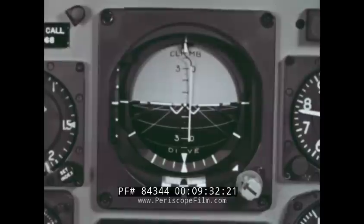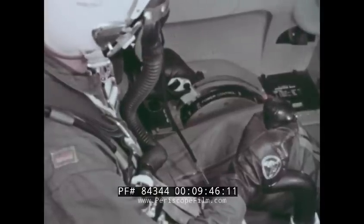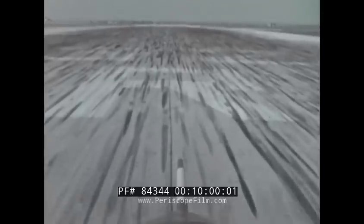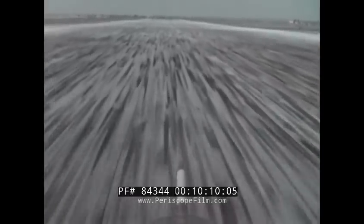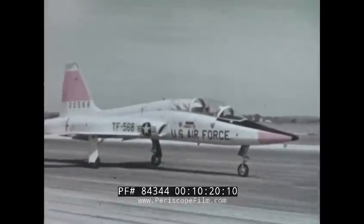Recheck your bank steering bar to see that it's centered. This bar will be used to maintain directional control during the takeoff roll. The instructor has turned over the controls to you, and you're ready for takeoff. To the instructor, the takeoff roll looks like this. But all you can see are the instruments. Just keep the bank steering bar centered, and you'll take off down the middle of the runway. Remember that the bank steering bar will only bring you back to your heading, not to the center of the runway. Therefore, keep the bar centered during takeoff roll.